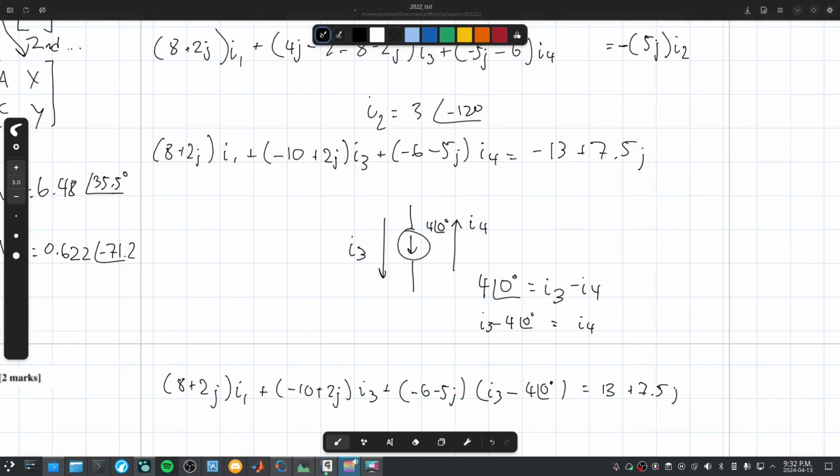I can't get it to show phasors, only complex numbers. Okay, so if you have the 991 ES, if you have an answer and you want to change it into phasor form, so like you already put in your equation and you want to put in phasor form, you do shift 2 and then select 3.